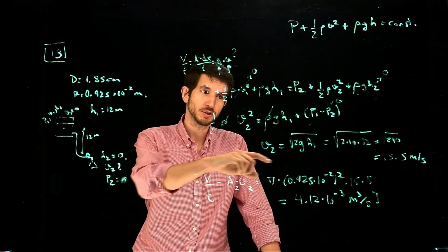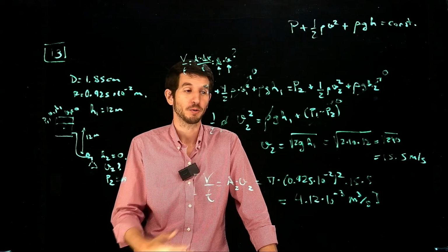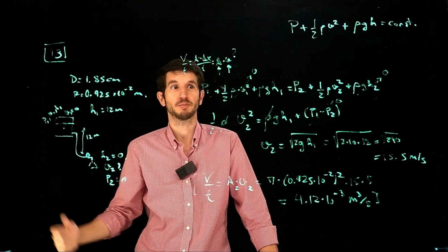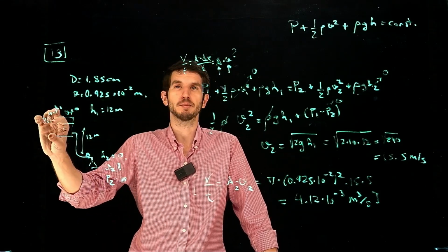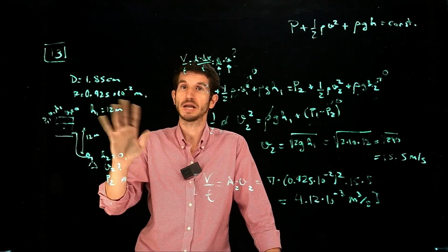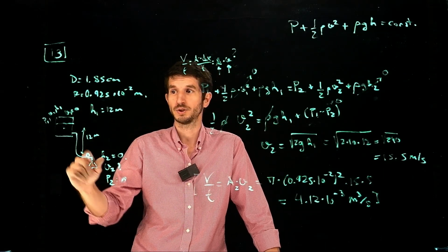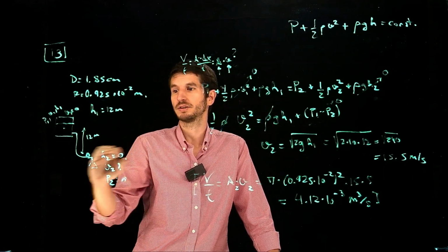And so the entire thing is you observe this equation, this reminds you a lot of the velocity of an object when you let it go. It's just purely due to the height, which is the same case here. Another story would have been if we had a pump here pressurizing the liquid, or a pump here just to extract it or something. But that's not happening here. We just open the atmosphere, we have the same pressure that's going to cancel. That's the first thing. Then observing the height and observing the kinetic energy is the same.